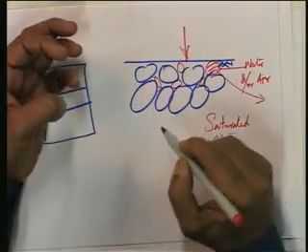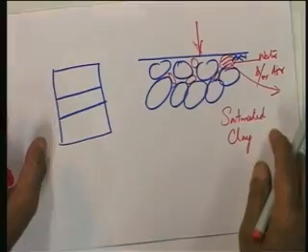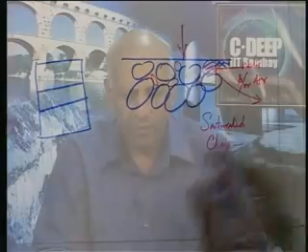The compression is going to take place because the water will move out of the void space when it is subjected to a load, and therefore, as the water moves out, the particles will get closer, they will reorient and readjust themselves, and the soil will become a little more compact and dense, and that is what contributes to the consolidation phenomenon.